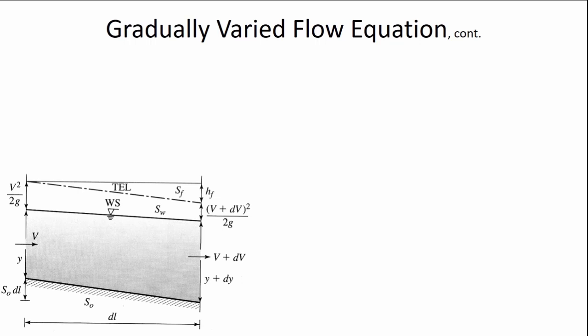And how do we know that this is non-uniform? Anyone? Okay, the slope of the water surface is changing. That's a good way to put it. Very good, yes. So for uniform flow, all three slopes would have to be equal to each other. The channel slope would equal the water slope, would equal the energy grade line slope, or the total energy line slope, S sub f. So those three slopes would be equal, but here we can see that the water's getting deeper in the direction of flow.